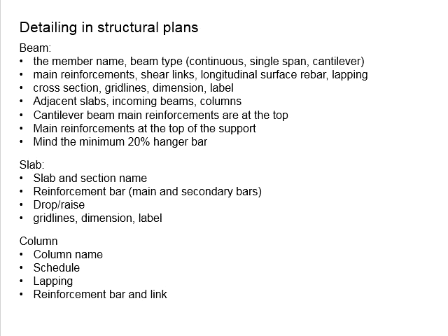Also, when you provide the reinforcement bar, remember that you need to provide the main reinforcement bar at the top of the support, as typically you are dealing with a continuous member. There will be moment at the midspan and at the support. At the midspan, tension will be at the bottom of the beam, and compression on top of the beam.